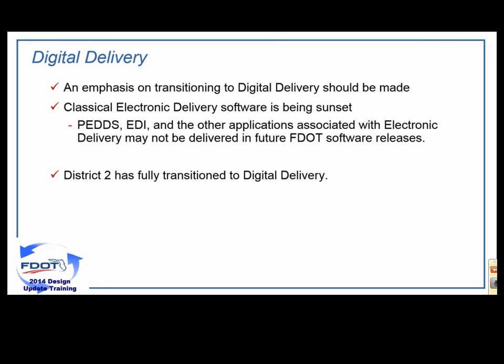It's a much easier process. Basically, it streamlines things. You can just create a print set from Sheet Navigator, print that out to a PDF, and then do your signing and sealing on the PDF using the digital signatures.